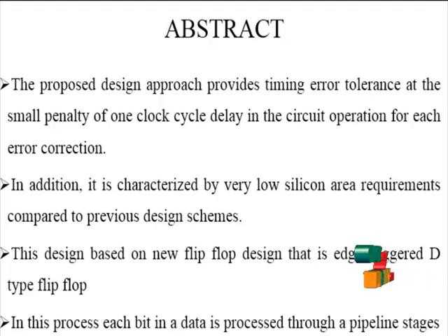This design is based on a new flip-flop design, that is, an edge-triggered T-type flip-flop. In this process, each bit in the data is processed through pipeline stages. This work presents a reliability-aware design technique which provides low power and cost-efficient timing error tolerance in nanometer technology. Small core designs are the building blocks for many core system on chip applications. This design is carried out in CMOS technology in the Tanner EDA tool.